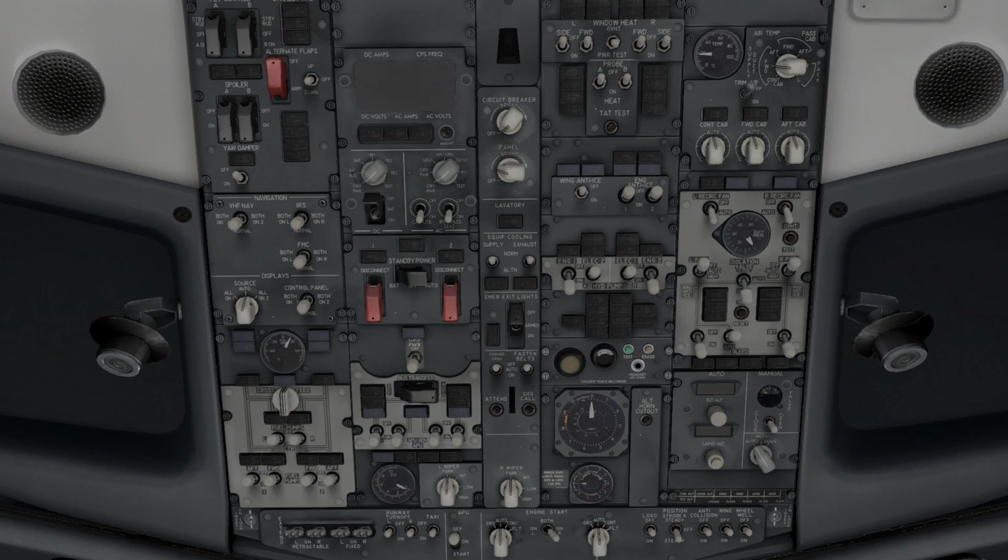On the overhead panel, we've got 4 rows and a skinny middle row. In the second row from the left, coming down under a blacked out display screen, you're going to see 2 knobs, and then to the left under the left hand knob we've got a switch labeled bat. Turn on bat, click on the little black guard to cover it. The switch above the bat in the second panel, we're going to click it up 2 clicks to the right to point to bat, and now in our electrical panel you can see I'm drawing 5.9 DC amps.